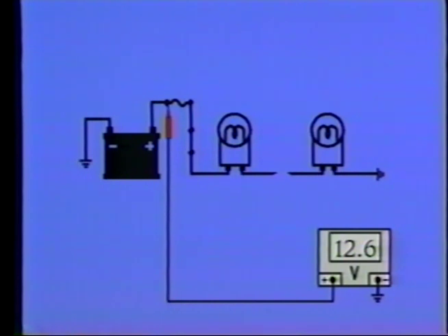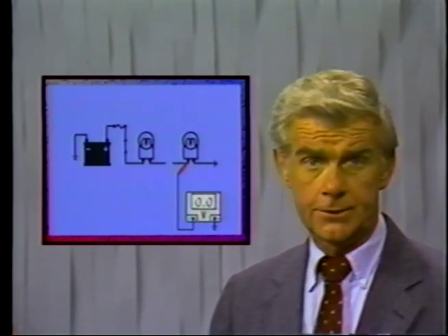If we do these same checks with a voltmeter between ground and the points in the circuit, we see full battery voltage, an indication of available voltage. At the break, the meter shows 0, indicating no voltage is left in the circuit. Defective fuses, switches, loads, or for that matter, any electrical component can be isolated as a cause of an incomplete circuit in this manner.